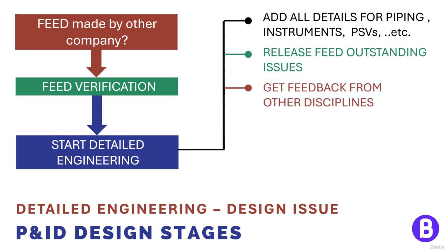We shall start to receive concerns from other disciplines. For example, the piping team is now preparing a much more accurate 3D model for the plant. So some clashes are identified, some piping routing may be changed, some issues may arise. So here we may change some pipe sizes or provide some solutions based on these issues. Remember that all these may also affect plant hydraulics, and the plant hydraulics may cause changes in pipe sizes. So these changes should also be reflected on the P&IDs.